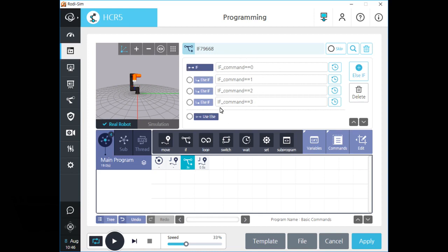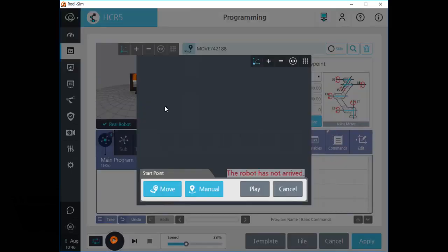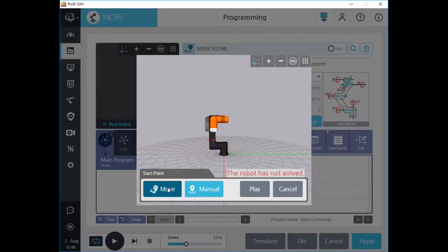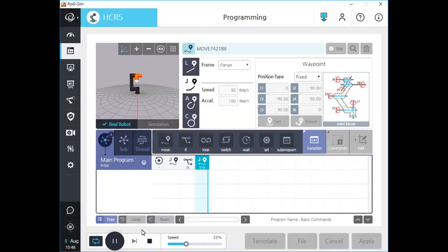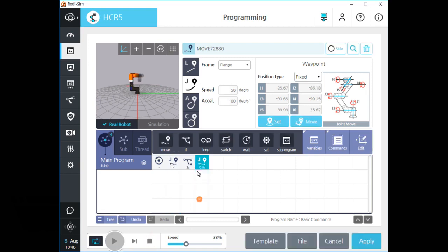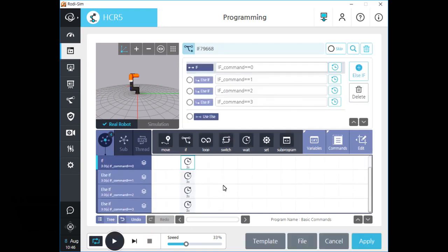In many cases, this ignoring will make serious problems and errors when you make an automation system with HCR. So, when you use the if command, please be aware that you need to use the else condition. After you click the small checkbox for the else function, you can see a new tree for this condition. Let's add a new message command to see a message when the else function is executed.